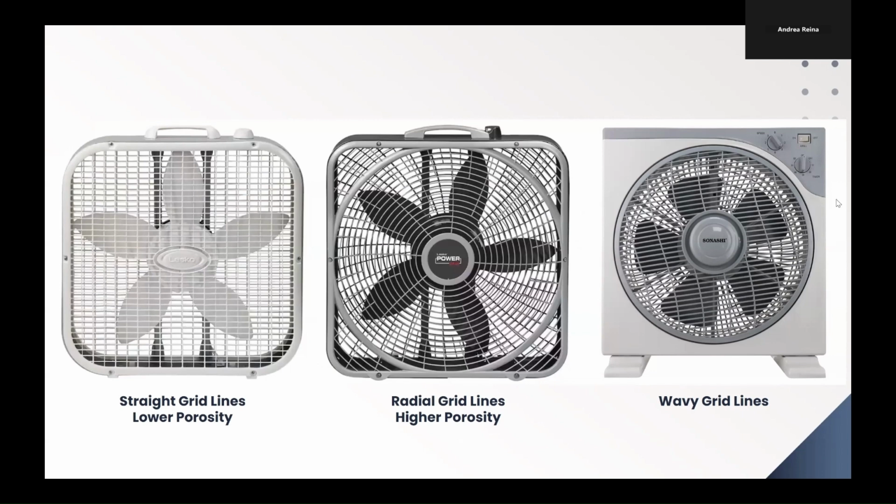Having a higher porosity would decrease the number of streamlines that interact with the grate. This decreases the pressure loss due to interaction, meaning smoother, faster airflow. The downside to this more efficient fan, however, is the decrease in structural strength.